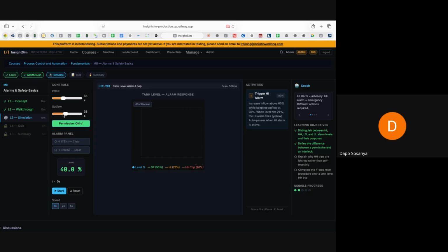And then at the outflow also, there is another valve that you can open and close within the range of 0 to 100%, so that if you want to increase the rate of outflow or reduce it or totally shut it off, that needs to be there. And you wire that valve also to your PLC. Are you following?